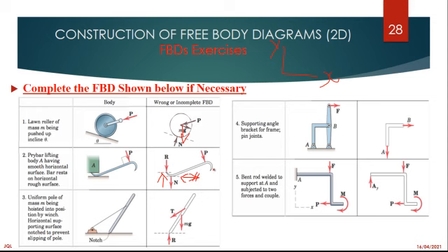The R. When you look at a notch to prevent slipping of the pole, it is not supposed to slip. It's not supposed to move in the X. It's not supposed to move in the Y, but it can move in the other direction. So even here, you need another force there, which will be Rx, where this is Ry.